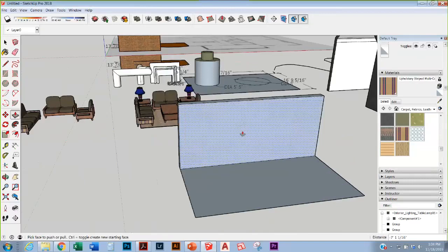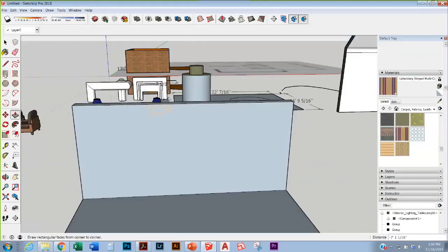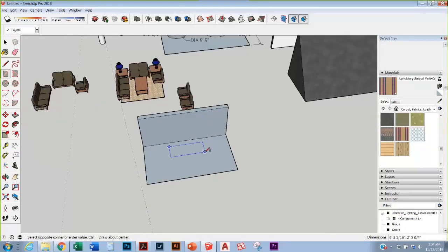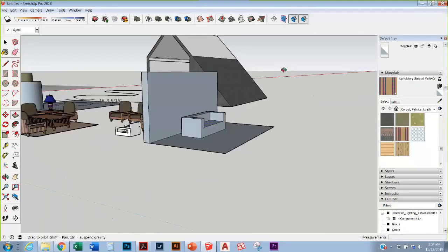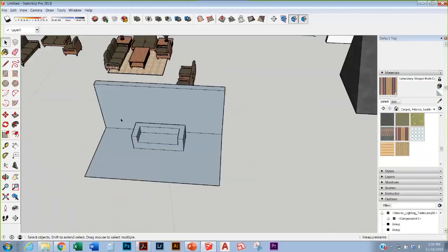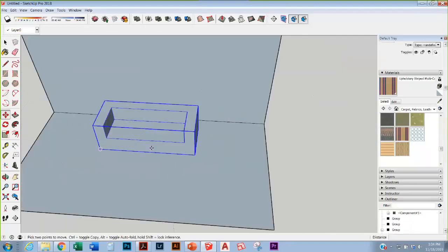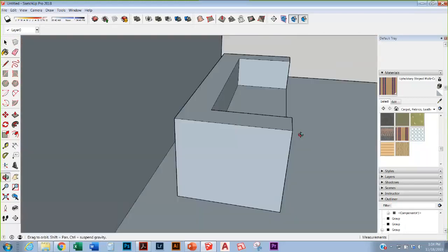So you can do anything on here. I oftentimes do things like say, hey, I'd put the couch right here. I'm not even modeling a couch. I just know that it's the right dimensions. If I wanted to show a couch, I could easily come here, here, here, here, push down, and now this looks enough like a couch, and then I can group those items together, and now my couch can move around separately. So that's a really fun tool to quickly make furniture pieces that act to scale, but are not necessarily physically accurate.